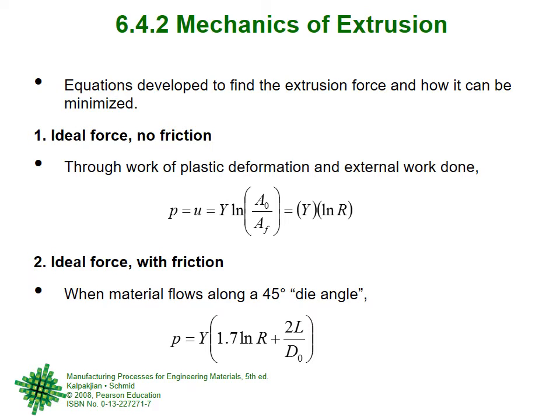So that happens here, that the material is being pushed, it hits the wall because the die is a 90-degree die. It cannot flow. But if more and more material comes, then a shear surface is formed at roughly 45 degrees angle naturally. So in this case, when the die is a 90-degree die, the force required or the pressure required will be high, but the material will still flow at 45 degrees.